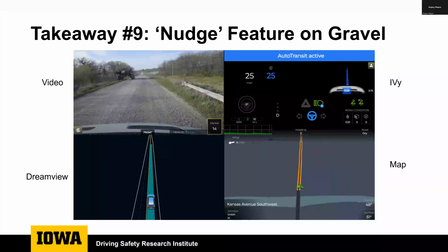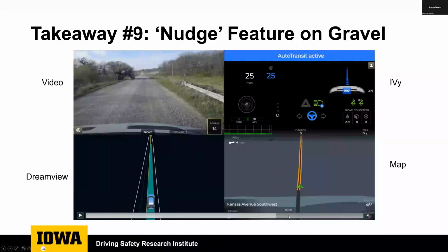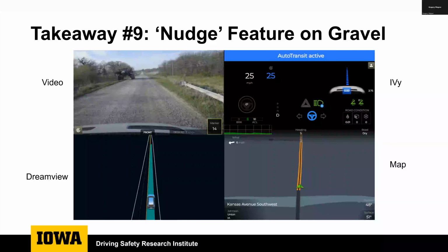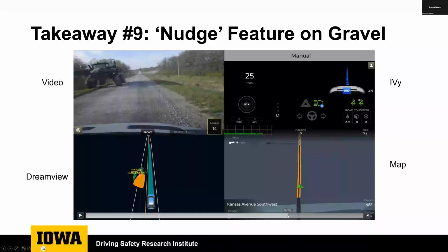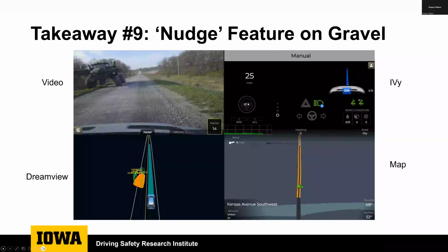Like one vehicle at a time. So therefore, one of the vehicles must yield the right of way, and in this case, the sprayer stopped for us. If we jump ahead a little bit here, you can see in the lower left of the Dreamview, the sprayer is actually identified as two obstacles by Apollo. You can see that by the text being kind of overwritten: two IDs showing up with two different speeds and the speed distance from our Ego vehicle.